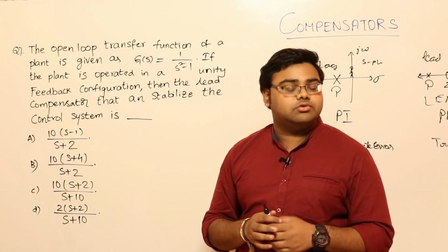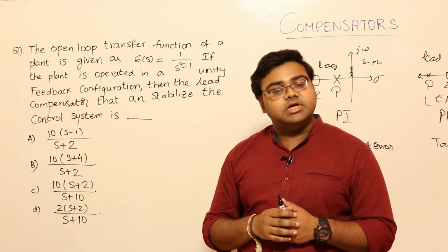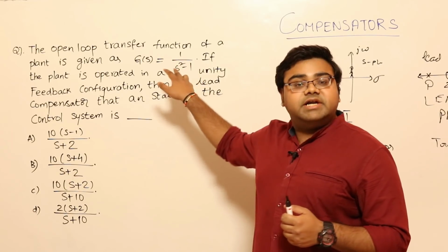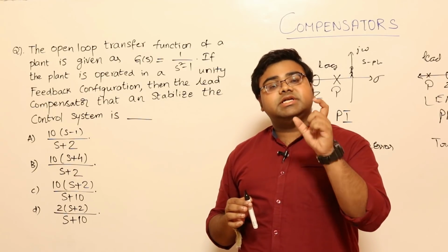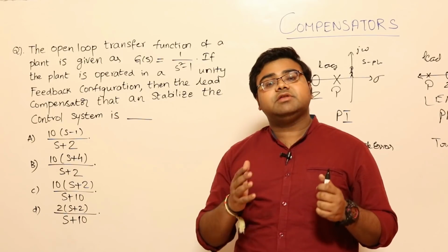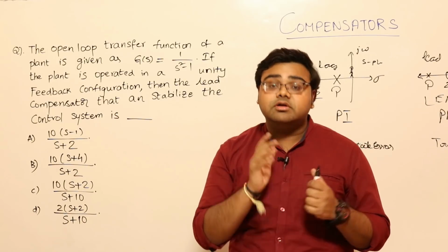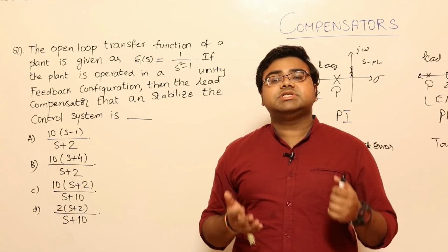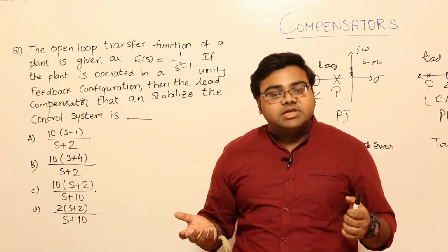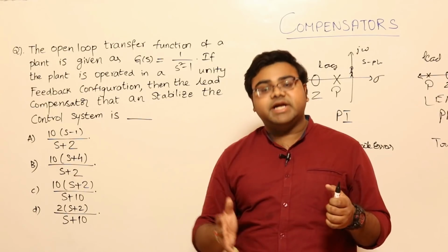Because of which, now I will tell you how, in deep analysis, this lead compensator is there. Even if it was not given, you could come to know, because it is 1 divided by s square minus 1, an unstable system. The transient behavior is what you will try to fix first, always. Then you will worry about steady state. Error and all come in a stable system. If you are not stable itself, first I have to try to stabilize you and bind you, right?